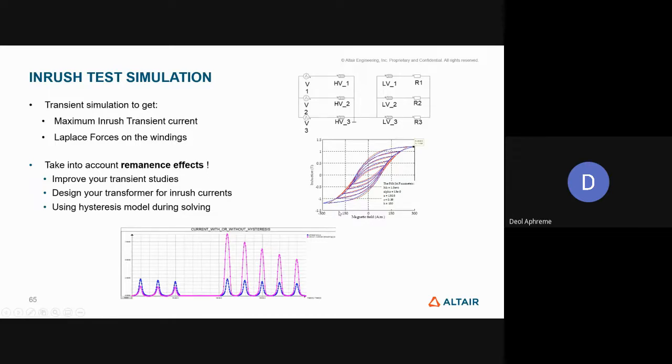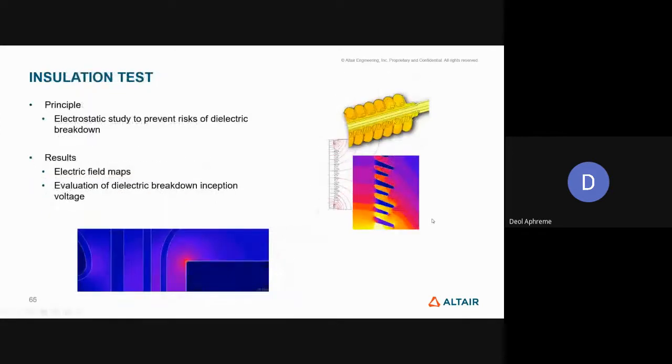Inrush current tests are done usually by manufacturers to understand the life of the transformer. They usually say 25 years, 30 years. So they usually do an inrush current test to understand the material characteristics, how it is changing, and there are quite a few coefficients that you have to enter. This is a fairly complex test to simulate, but if you have all the physics parameters, which is the value of alpha, A, K, C, and K, if you have all these quantities, you can definitely simulate them and speak about the aging of your transformer.